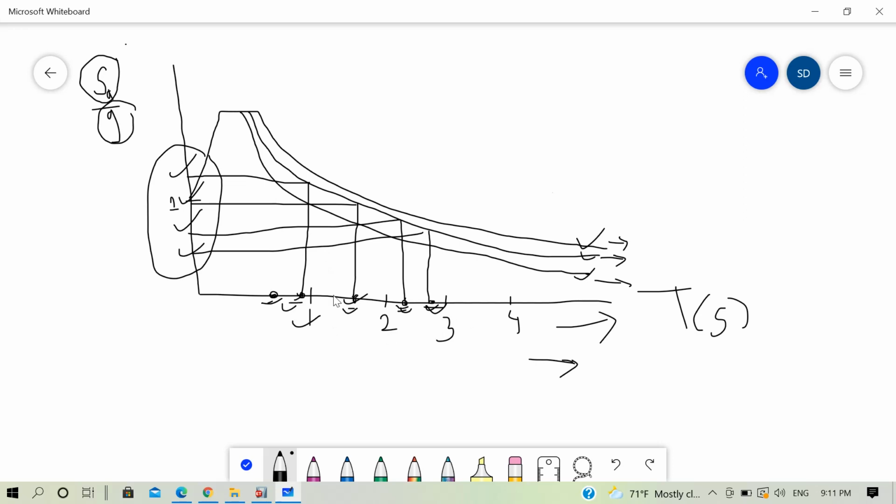So you get this? If you don't understand this, let me repeat once again. Response spectrum analysis is a multimodal or multiple modal combination method in which, as we have already discussed in our previous lectures, the responses from different modes of vibration are combined using a particular combination rule, such as the SRSS method, CQC method, or absolute sum method. So what a response spectrum analysis does is combine the responses of our building from different modes of vibration. And to get the response from each mode, the acceleration is applied to our building corresponding to each mode of vibration.